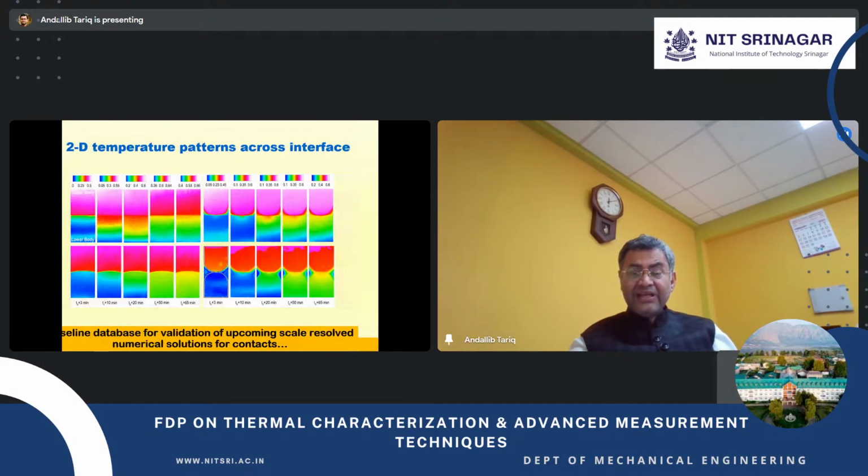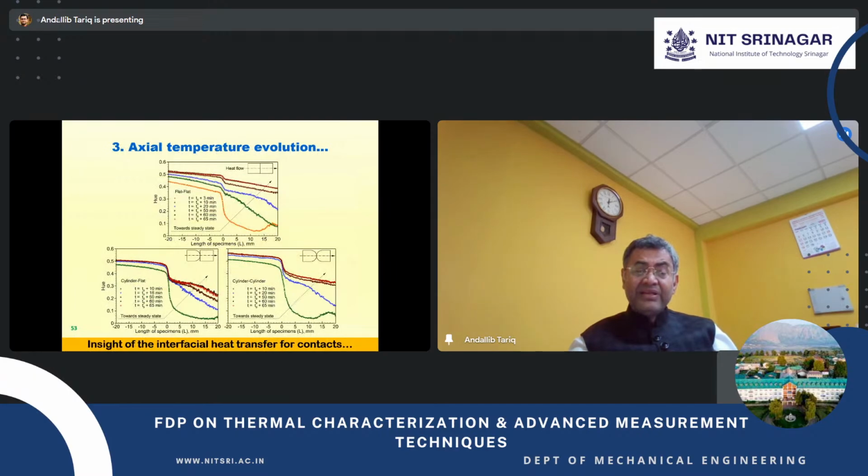Okay, so this is the thing, and these are the transient temperatures. Basically, how the temperature will evolve. You can see that the upper temperature is constant, and when it comes in contact with the lower temperature, the lower melting surface, heat flow will occur and it will get stabilized. It will take a typical temperature profile, and the temperature gradient in the water, these two will grossly follow, dictated by the Fourier conduction law.